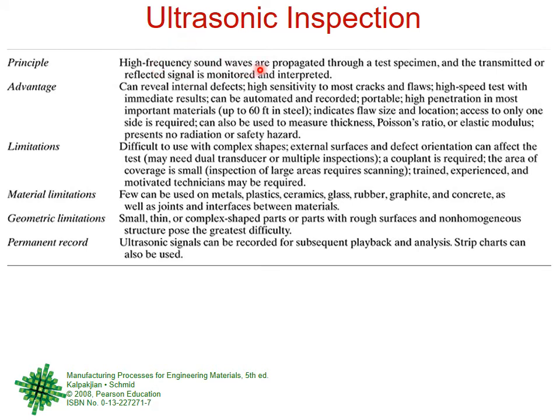So high frequency sound waves are propagated or sent through the test specimen, and the transmitted or reflected signal is monitored and interpreted. You know, this is a very common thing in medical inspection also. Ultrasound and so on is there. So they send sound waves through your body, different parts of your body, whatever they are inspecting, and by the returned signal they can see the defects and so on.